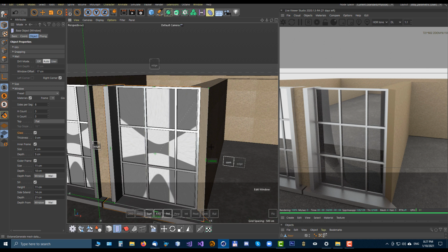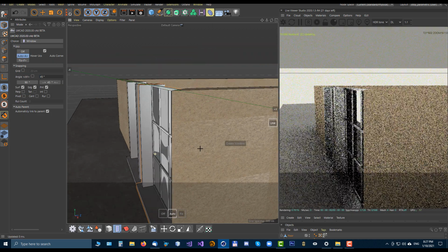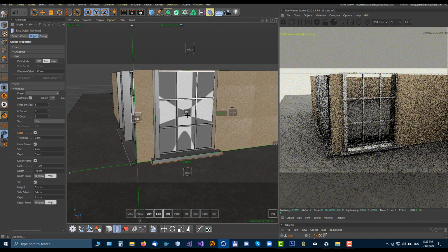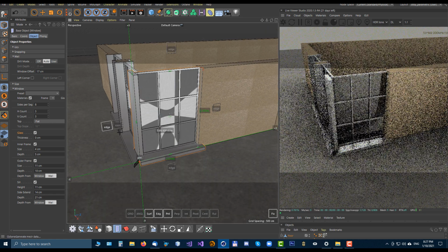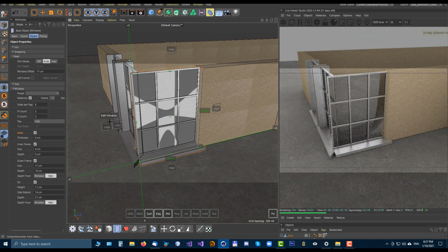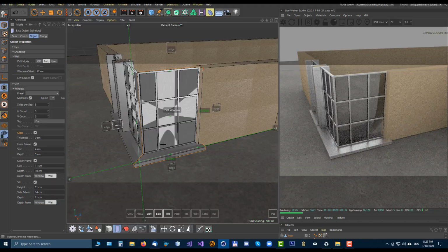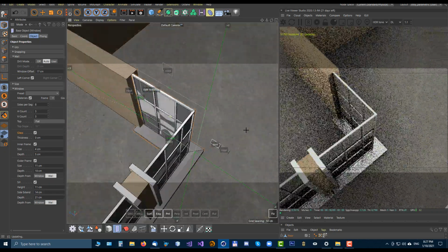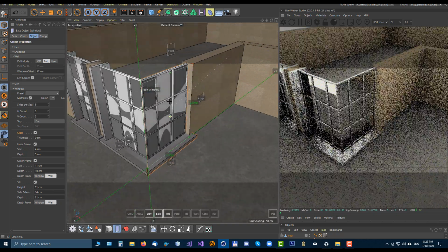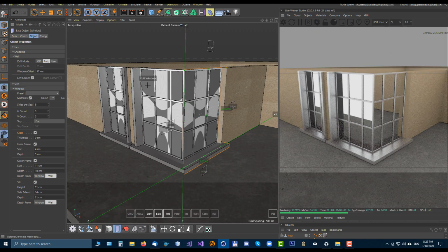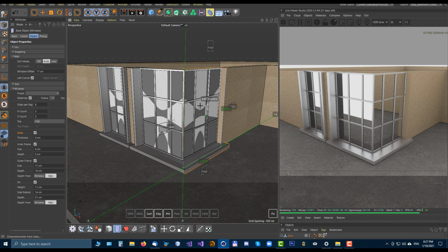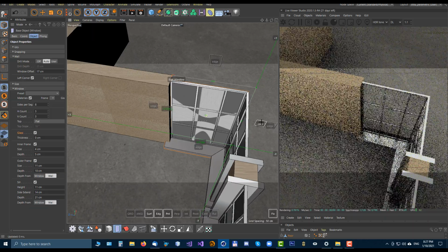feature is this fix button. You can remember or fix current size of the tool with fix button, and when you apply to somewhere else, it is created with same size. This is very useful. And now if I use the corner button also on the second side of the corner window, you can see how pretty nice corner window we have created. Together with fix mode, these both windows are identical, and also we have created very nice and clean corner.